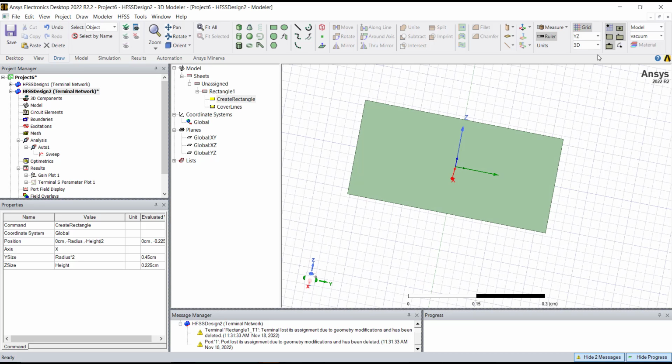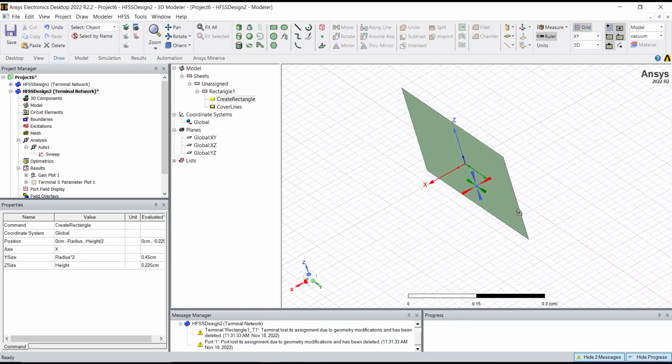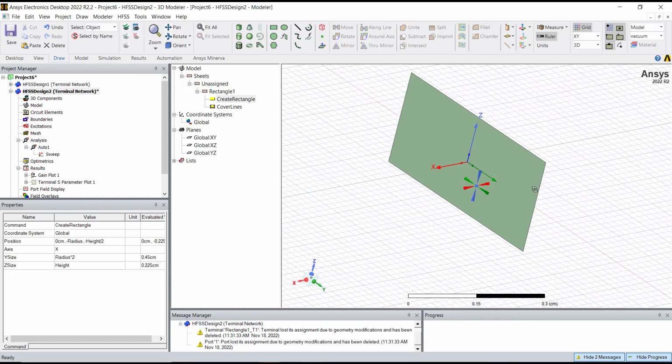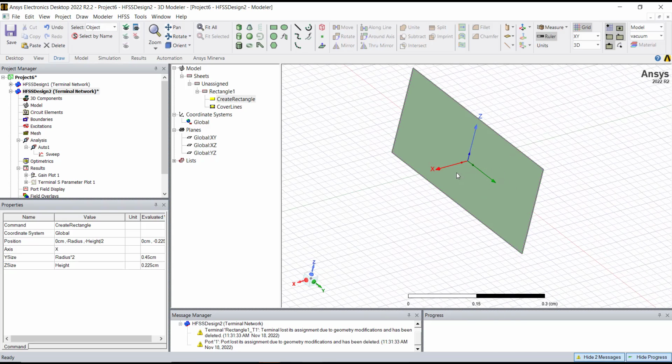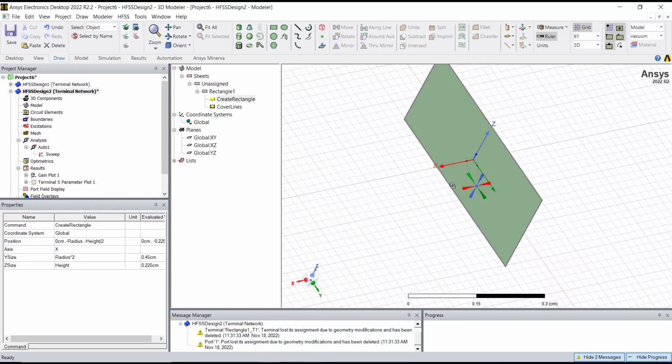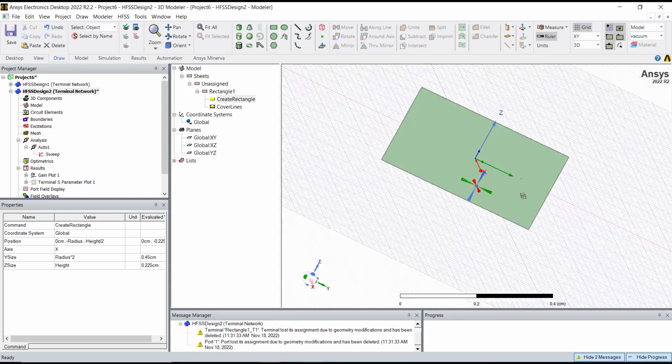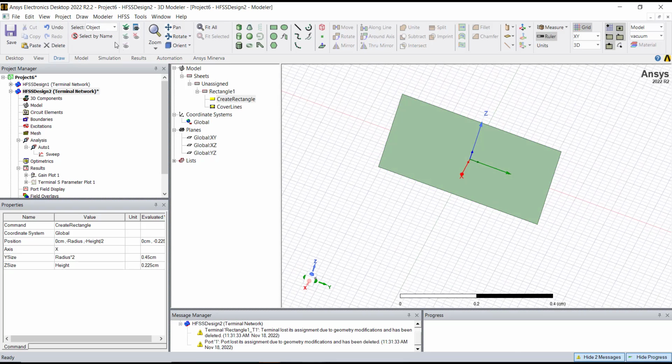Let's move on. We're going to change the plane from the YZ, just like before. We created the cylinders in the XY plane. So that's a perpendicular plane to the one that we were just in. What that means now is that when we create the cylinders, the circle is going to be defined in the XY plane, and then the height is going to be referencing the Z dimension. Okay, so let's just go ahead and do that, but we're going to do it the same way.